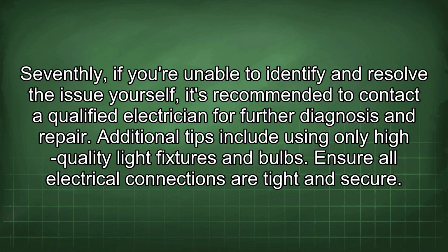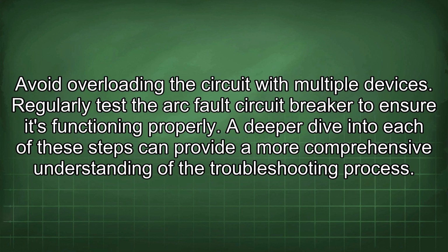Ensure all electrical connections are tight and secure. Avoid overloading the circuit with multiple devices. Regularly test the arc fault circuit breaker to ensure it's functioning properly. A deeper dive into each of these steps can provide a more comprehensive understanding of the troubleshooting process.